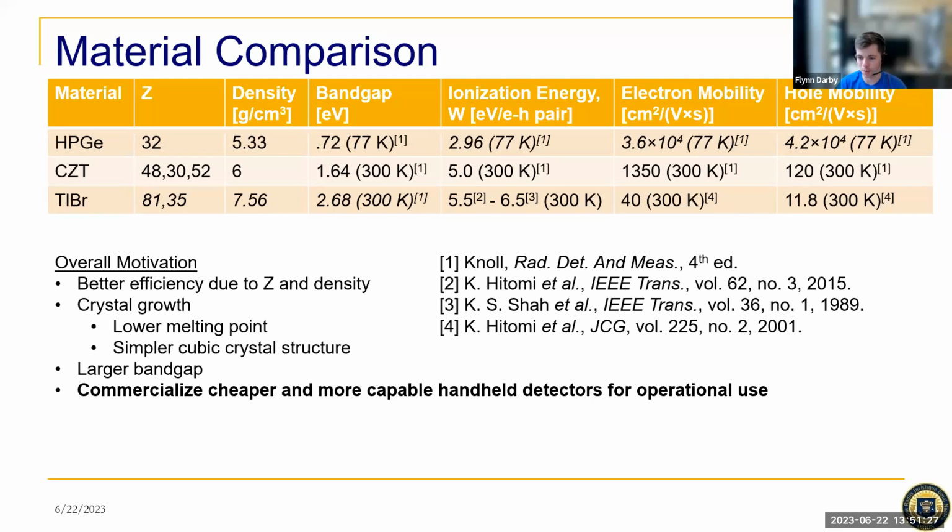Got it. Thank you. And we just had one more pop up. Abhishek is asking, there may be more semiconductor materials other than these three we covered. What is the most efficient until now for gamma detection? Oh yeah, I forgot to mention, I only talked about 3, 4, 5 materials in this presentation. But there's a lot of different semiconductors out there. Other than CZT, there's cadmium telluride, silicon. I think there's a couple out there using gallium or lithium for neutron detection. So yeah, there's a lot out there. These are just the ones that I have the most experience with.